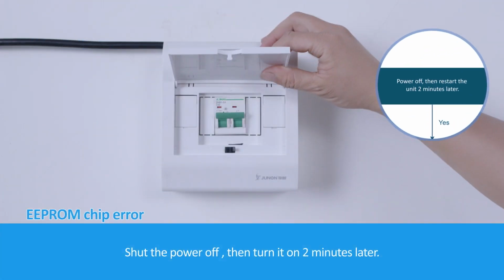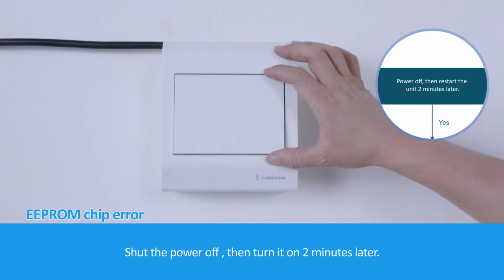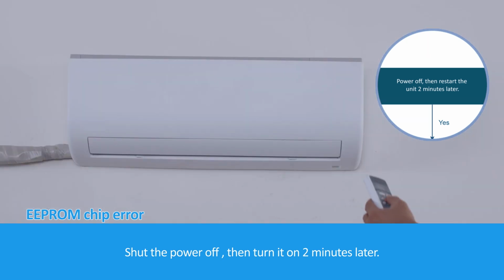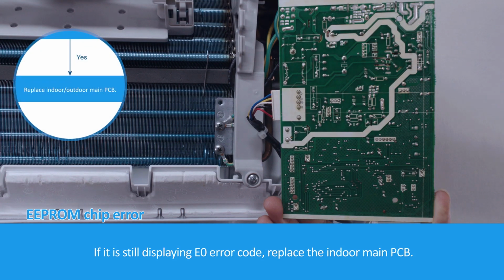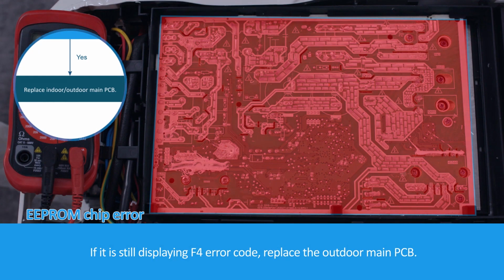Shut the power off, then turn it on 2 minutes later. If it is still displaying E0 error code, replace the indoor main PCB. If it is still displaying F4 error code, replace the outdoor main PCB.